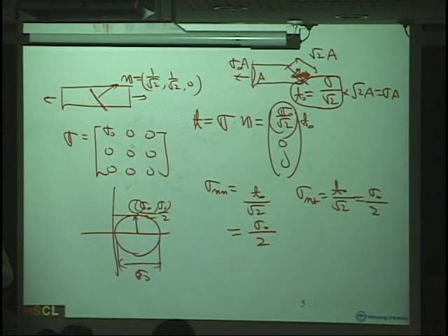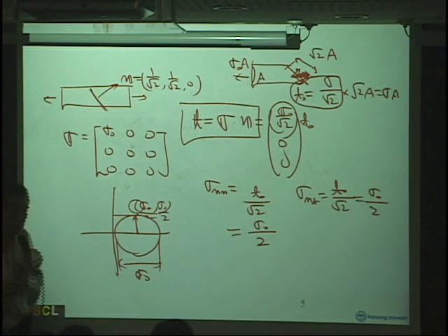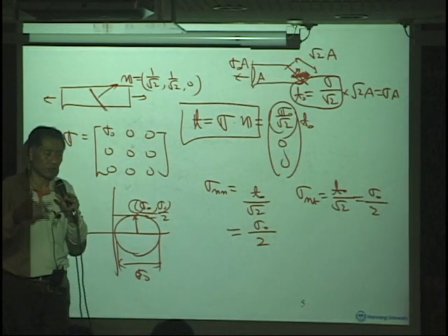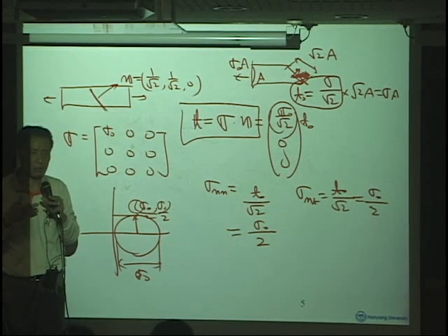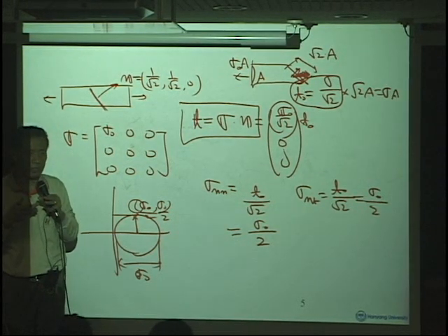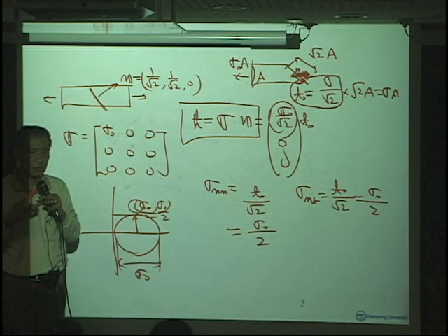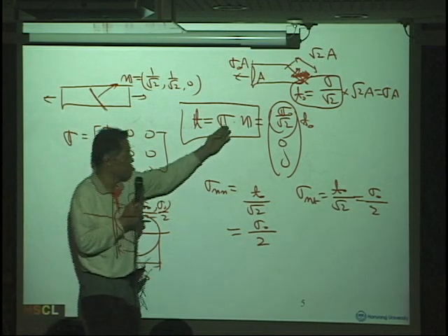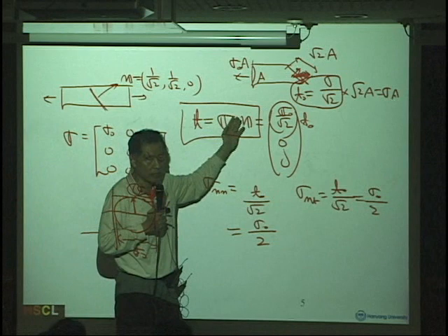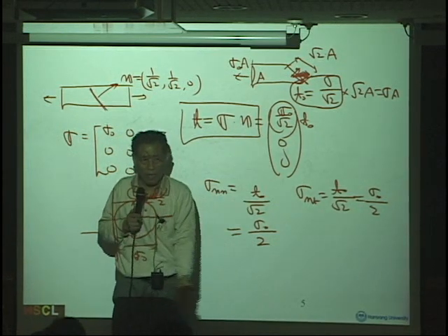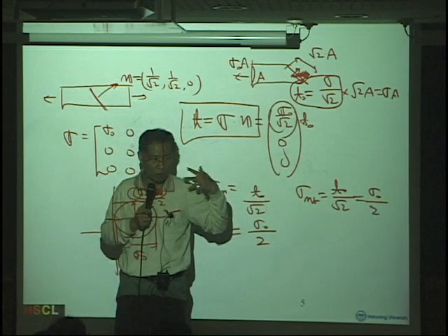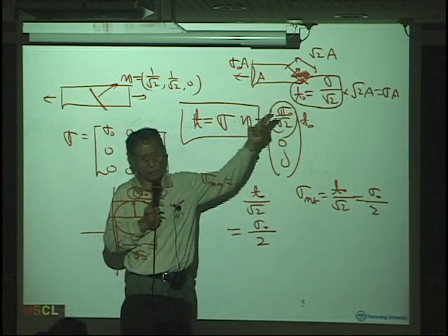So it is really good to know: traction is whatever distributed load appears in the cross section, and it is simply sigma times n, a matrix and vector product. What is n? n is the unit normal vector to that surface.